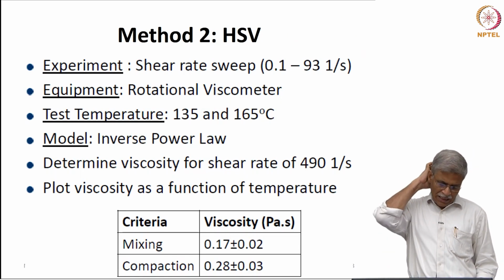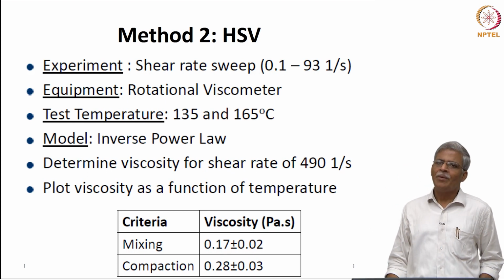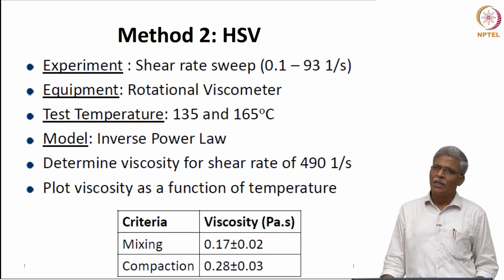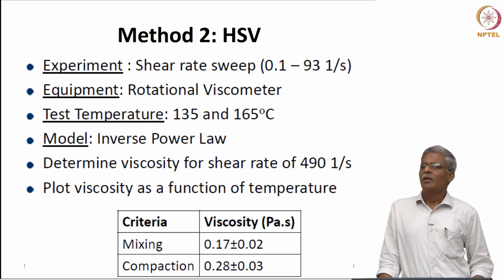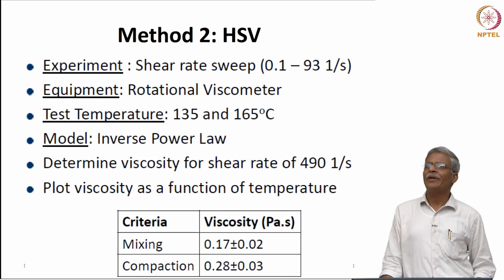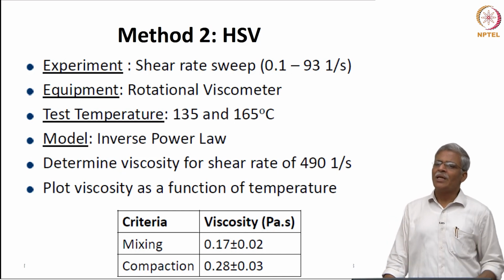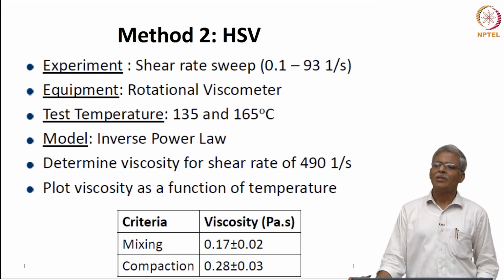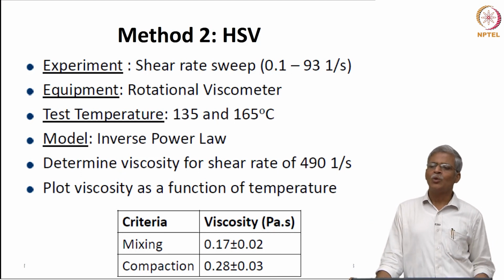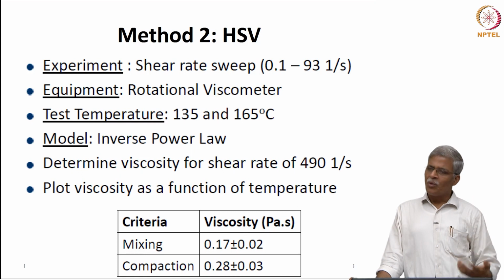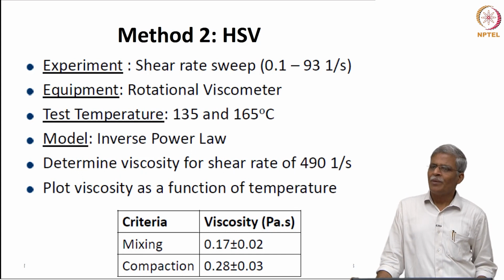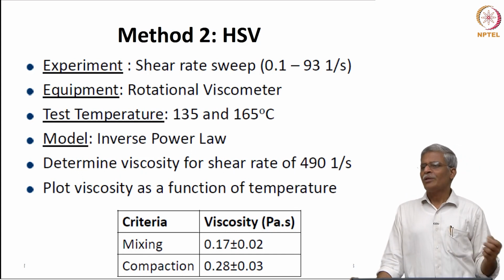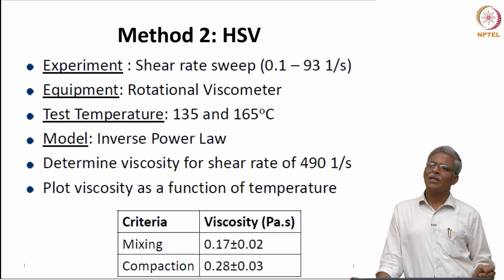Now, let us take a look at the second method. Okay, I am basically discussing only the methods. The details associated with using a specific model, using data to calibrate and finding out the parameters is basically outside the scope, because you need to have some understanding of how to use a non-Newtonian fluid model, find out what the parameters are, use appropriate algorithms, maybe try to use MATLAB, and then use these parameters to compute viscosity, and then plot viscosity as a function of temperature.